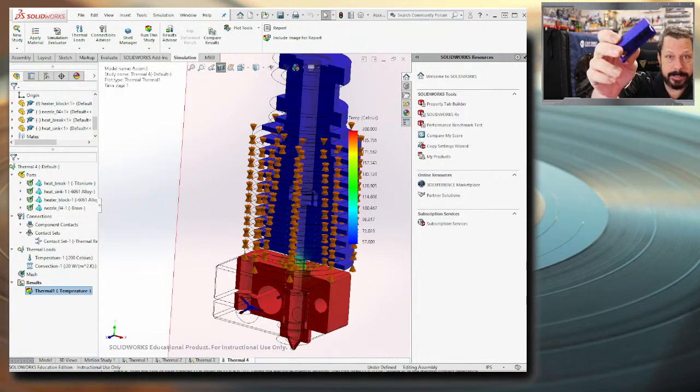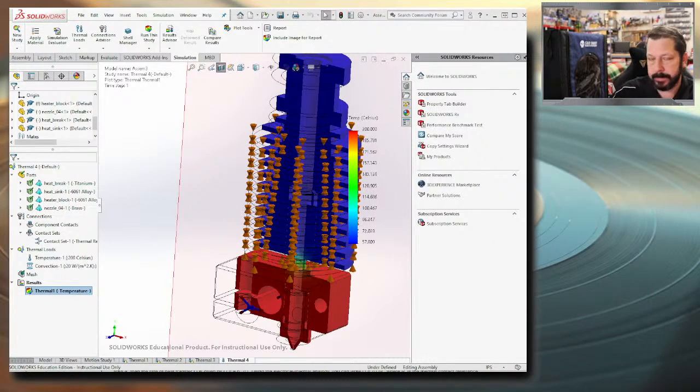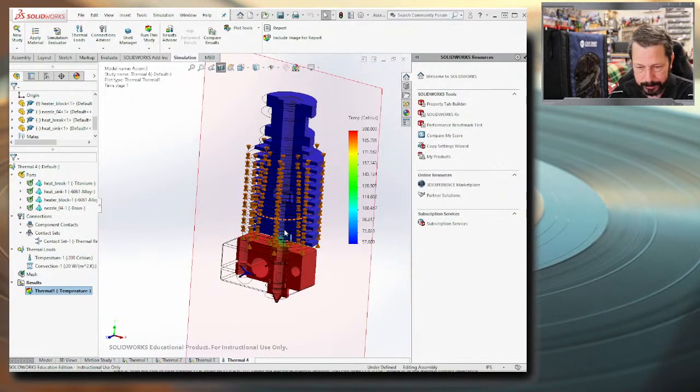And again, that's the thing I said, that you can print those pretty easily, or you can cut them other ways. Just be sure you're using a sharp blade so you don't squish the end of the Bowden tube, and make sure that you're getting it as square as you possibly can, so that there's not a gap between it and the surface that it's sitting on inside of the hot end. So hopefully that will give you enough little hints of what to check when things stop working.